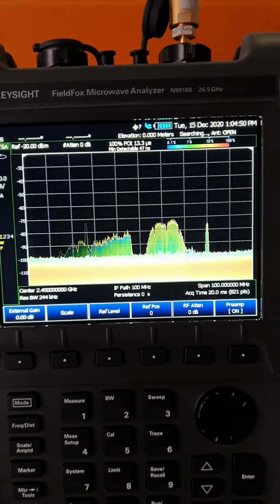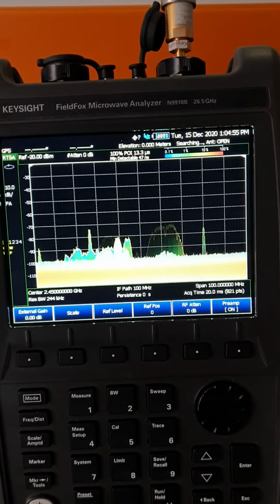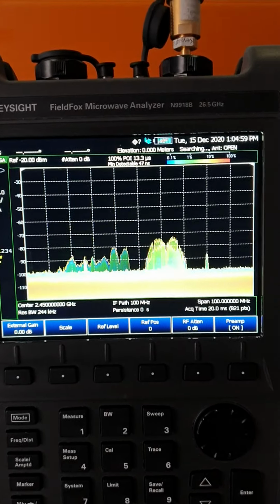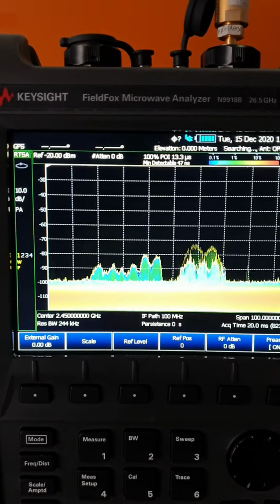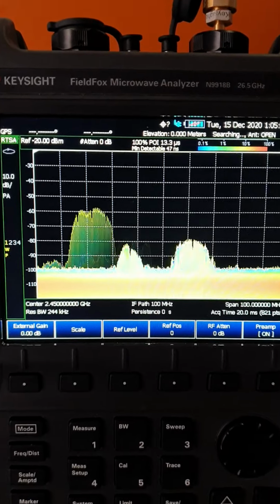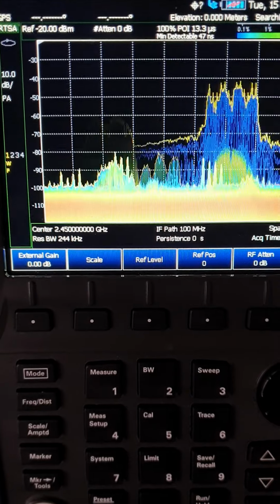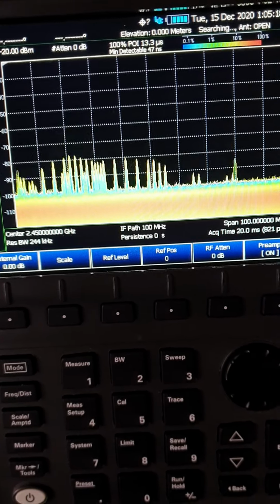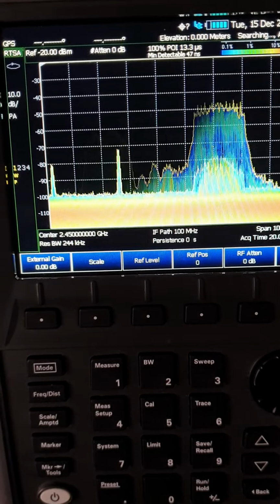What the real-time spectrum analyzer does is use FFT to capture the spectrum very, very quickly, taking a chunk of spectrum and digitizing it rather than sweeping. And so what you'll see now is those signals far more effectively, and what you'll also see is the different layers of signal, if this will stay in focus. You'll see here how the various signals are all sitting at different points in the spectrum, and which ones are overlaying and popping up over the top of each other.